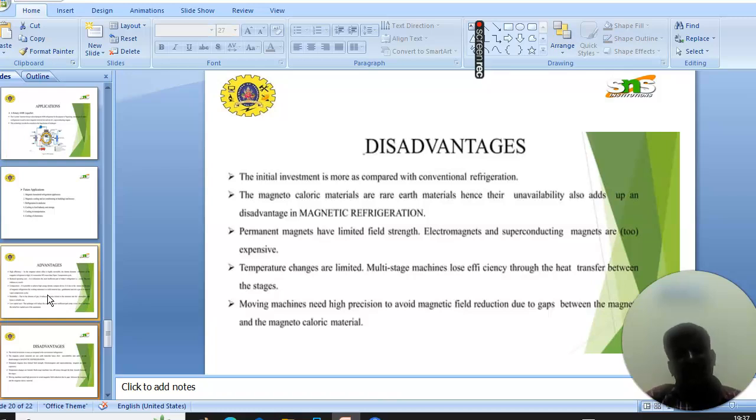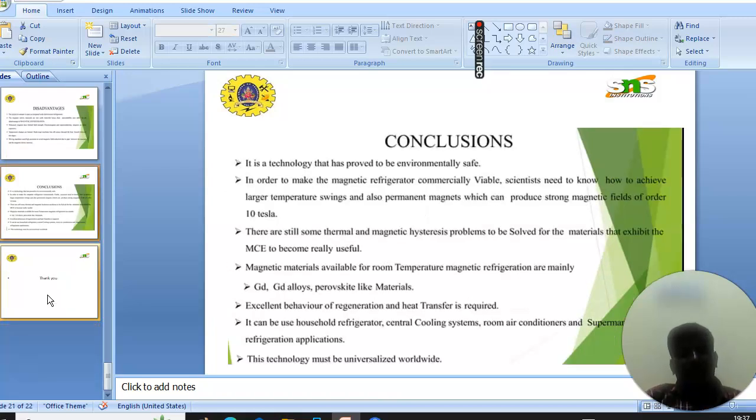The next is applications. Applications include a rotary AMR liquefier. In this, the cryofuel systems group is developing an AMR refrigerator for the purpose of liquefying natural gas. A rotary centrifugation is used to move magnetic material into and out of a superconducting magnet. This technology can also be extended to the liquefaction of hydrogen. Future applications may include magnetic household refrigeration appliances, magnetic cooling and air conditioning in buildings and houses, refrigeration in medicine, cooling in the food industry and storage, cooling in transportation, and cooling of electronics.